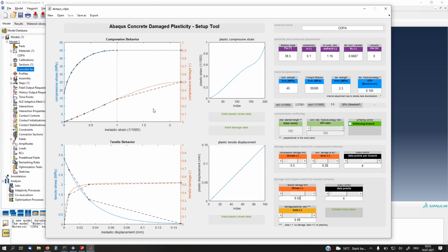I did some nonlinear analysis of big concrete structures, and I saw that actually accounting for compressive softening is very, very important, because you're just going to get random results for your load history and whatever you want to calculate. So accounting for that is actually quite important.